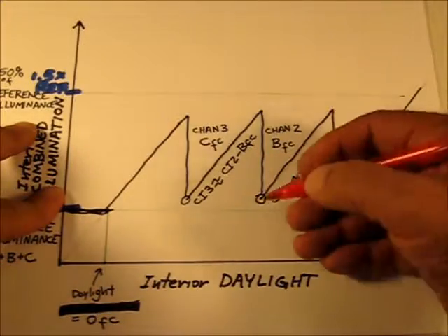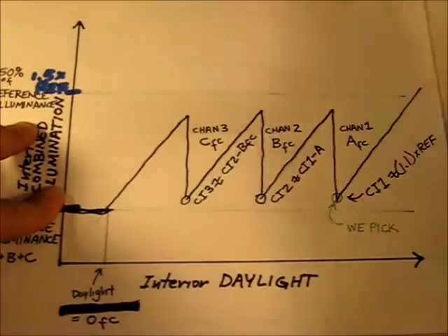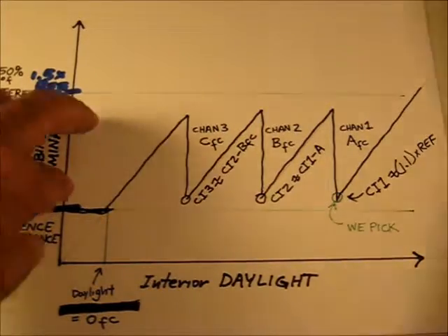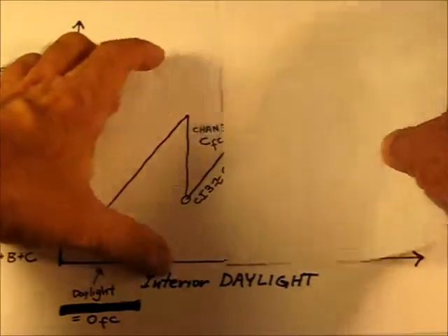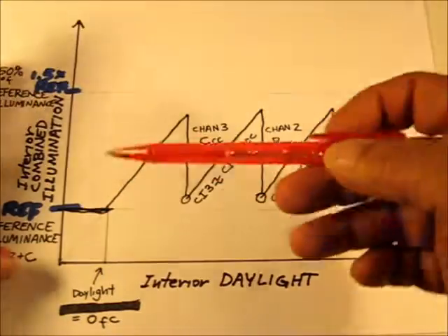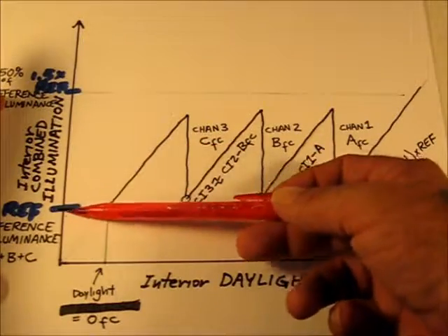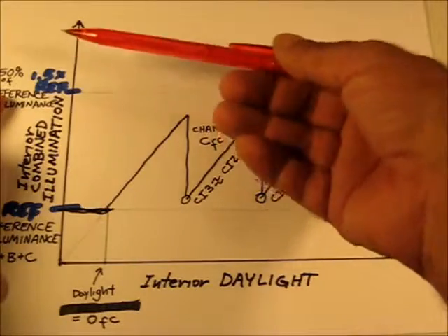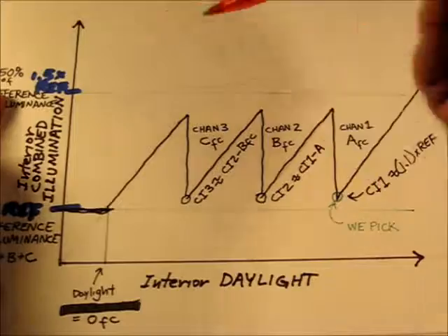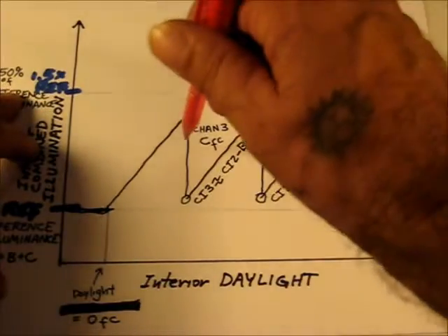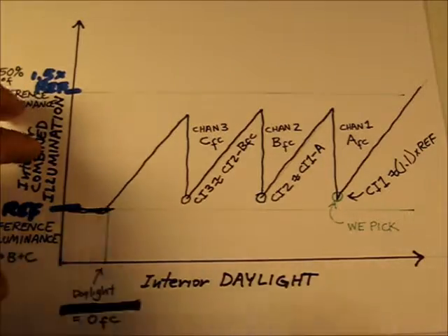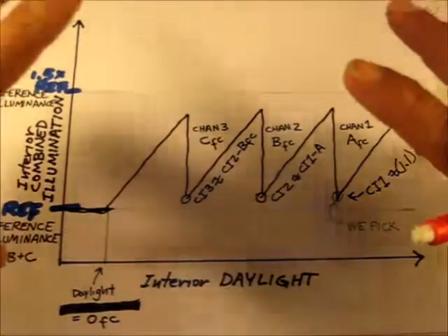So these are likely to be shifted up and down a little. Deal with it. The next thing we have to do is establish our deadband. Well, here are things that are set in stone for us. We took a good measurement of the reference illuminance. We know what 1.5 times that is, or 150% of it. And we know what the contribution of our switched lighting is at our reference location.